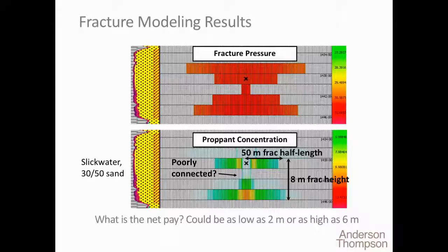job was conducted. It's a slickwater, 30-50 sand. We're seeing that the slickwater wasn't able to carry this stuff up very well. We're seeing that the sand dropped, and not only did it drop, but the fracture results showed a very poor connection.